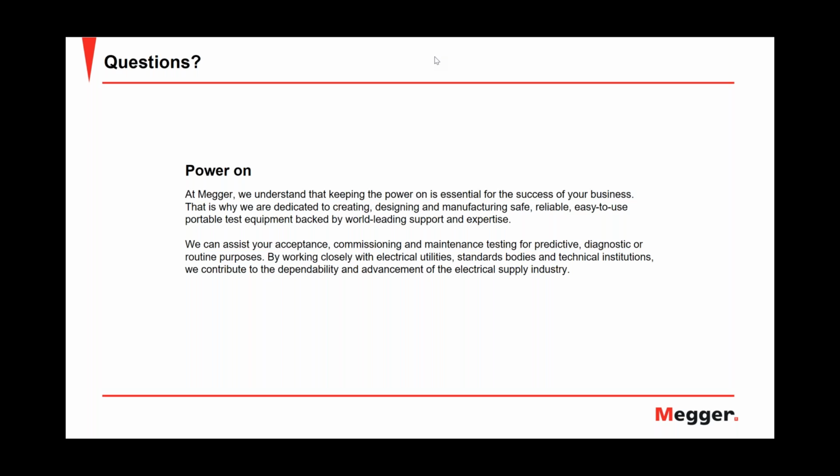So if you have a 16 kV thumper for this test, just put it to 16 and let it ramp up. Because you assume it's a faulted cable, which failed at operating voltage, that is what caused the failure. It saw operating voltage, and then the insulation gave in. So you expect the breakdown to happen at a lower level.